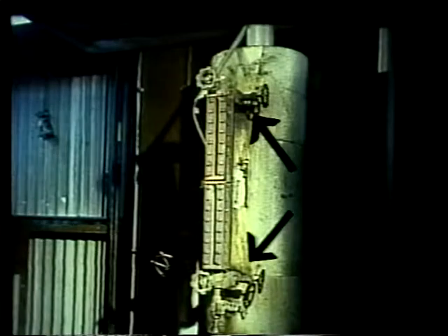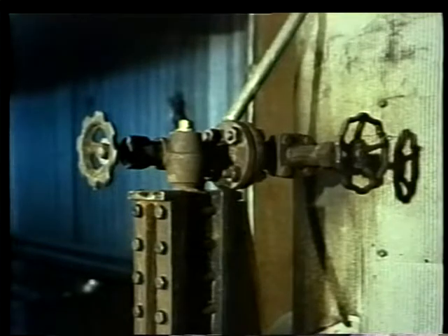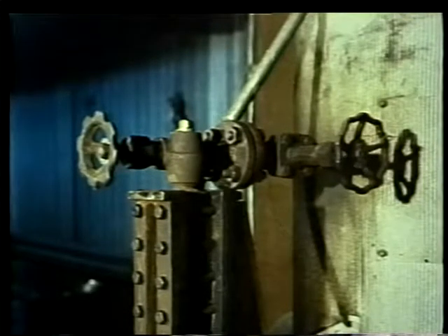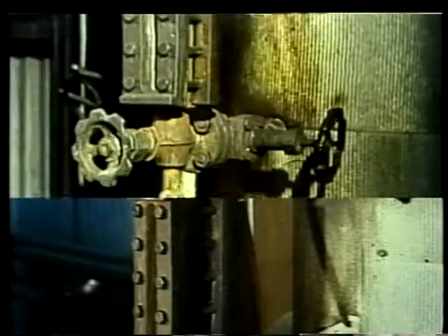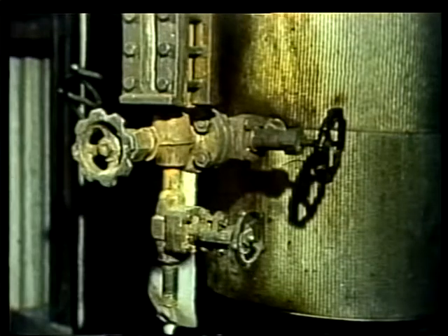Flat glass gauges have valves used to close the upper and lower connections when maintenance is required. When closed, these valves prevent fluid or vapor from entering the gauge glass. The gauge may have two valves in the top and bottom connections to ensure complete isolation.